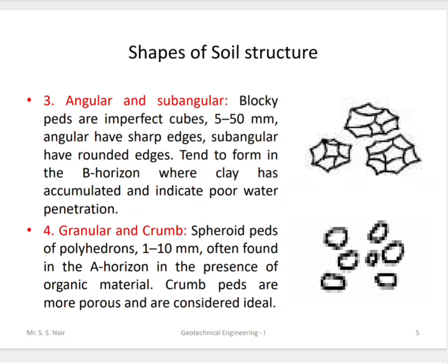The third one is angular and subangular blocky. Blocky peds are imperfect cubes of 50 mm, angular having sharp edges and subangular having round edges. Formed in the B horizon where clay has accumulated and indicate poor water penetration.